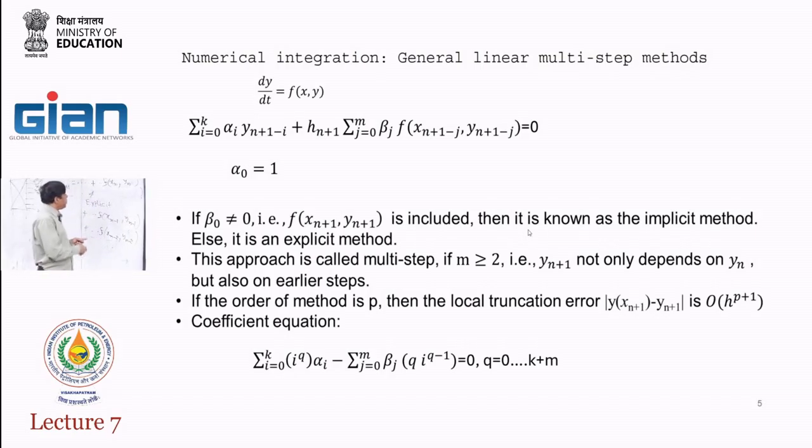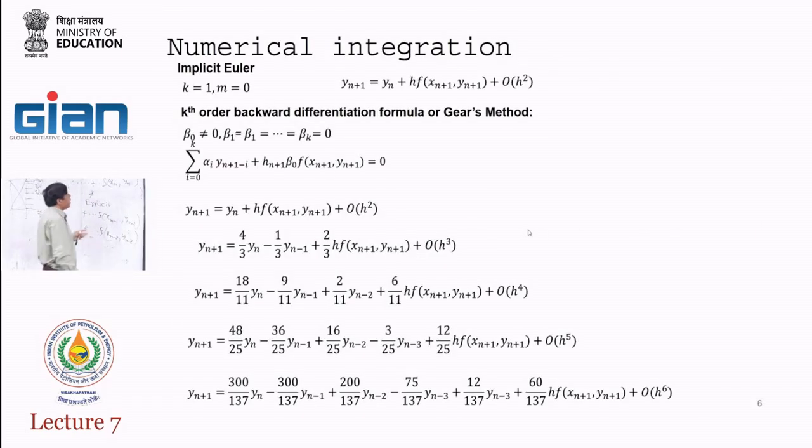But this gives you a variety of methods. When you go to Aspen Custom Modeler, it will give you an option, say Gear's method, and it will ask for the maximum order, and you say yes, 6 or 5 or whatever. It's up to you.